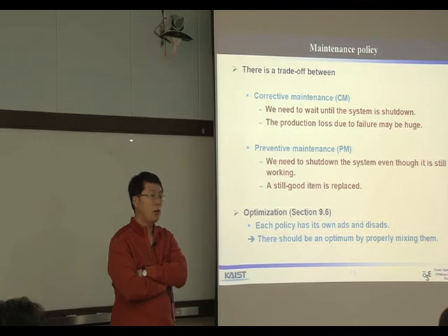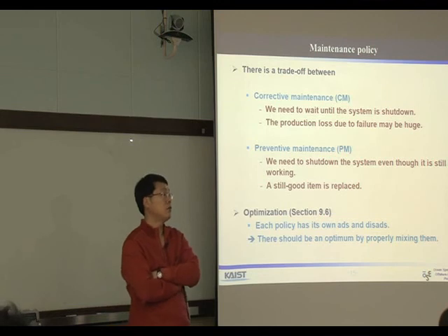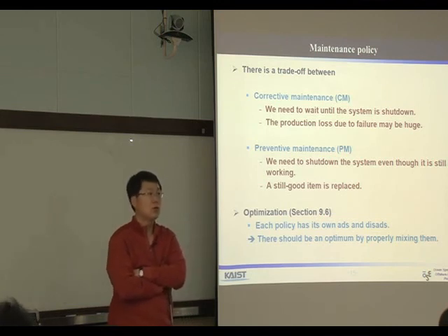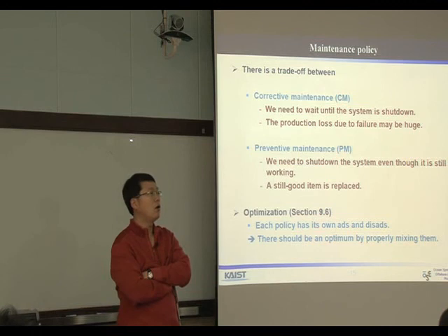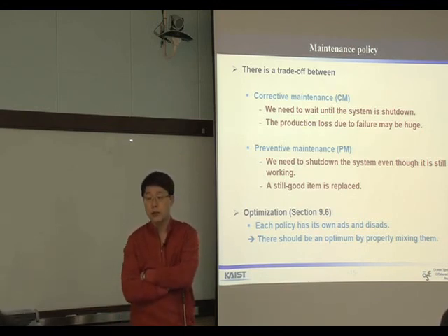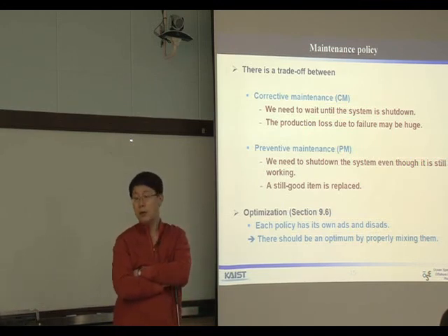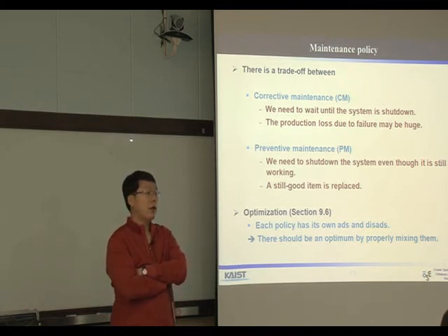But the money is small compared to the cargo the ship carries. So the stop of the ship engine can cause many damages. So with condition-based monitoring, measuring the temperature, pressure, vibration of the engine and doing maintenance based on the information, this kind of maintenance is called condition-based maintenance, as we already learned. That kind of technology is currently in application.